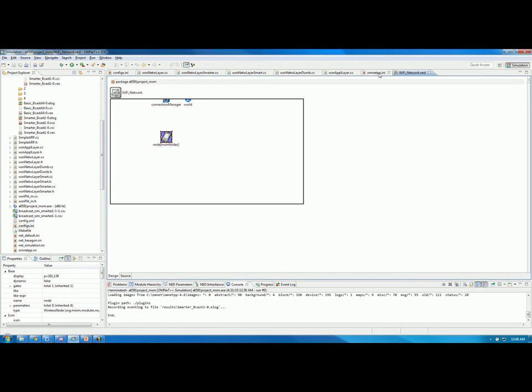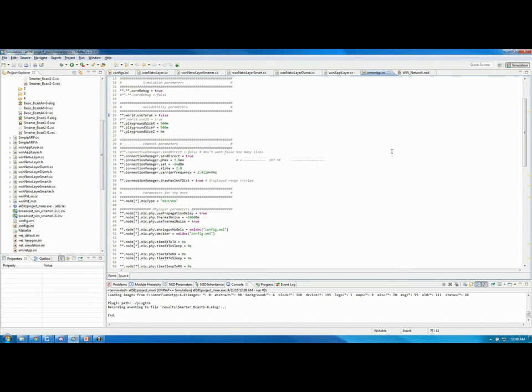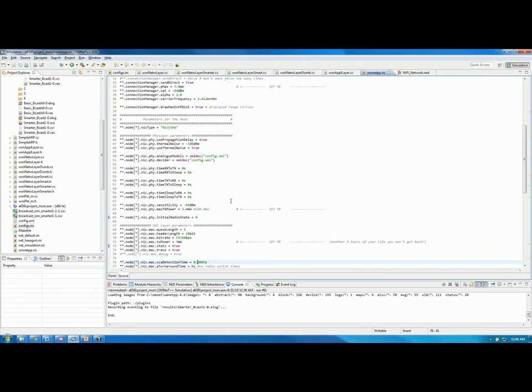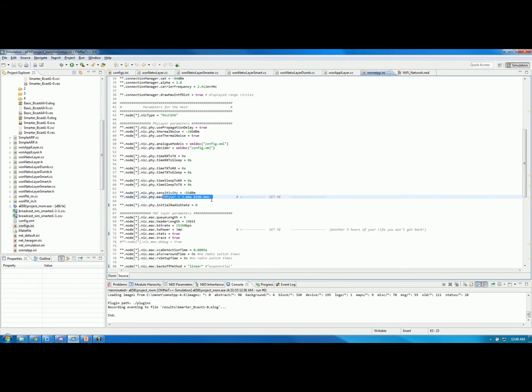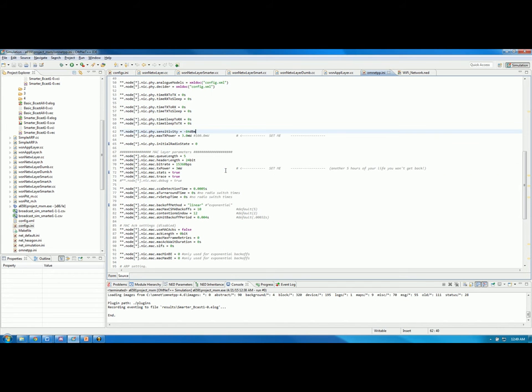Speaking of configurations, everything is done in essentially a configuration file where, like I show you here, different channel parameters, different physical layer parameters such as the transmit power and the noise level sensitivity of every node. Again, this can be configured either in a configuration file or in real time during the simulation. Do I want to increase my transmit power? You can also model battery life, and that makes OMNet a really great tool.